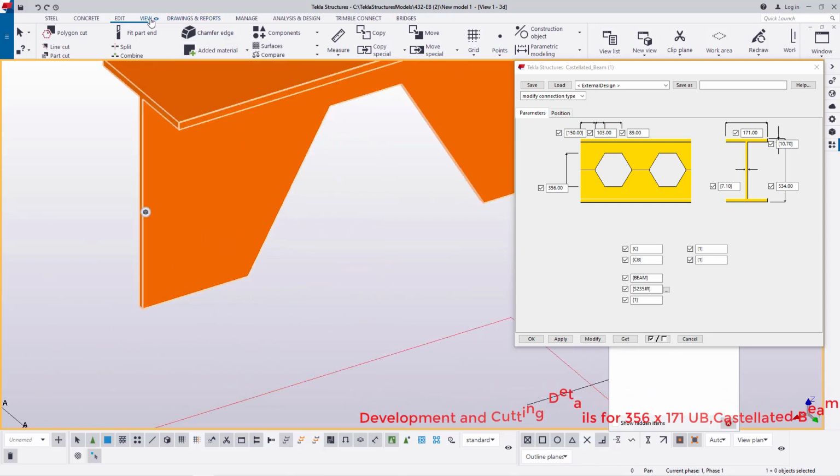And remember, the moment you save in Tekla Structures, there's no way going back. You've completely lost your way back to where you came from. So if you intend to go back in any kind of modeling in Tekla Structures, please don't save. Or if you're done with whatever modification, you can save, because you're confident enough that you will not be going back.